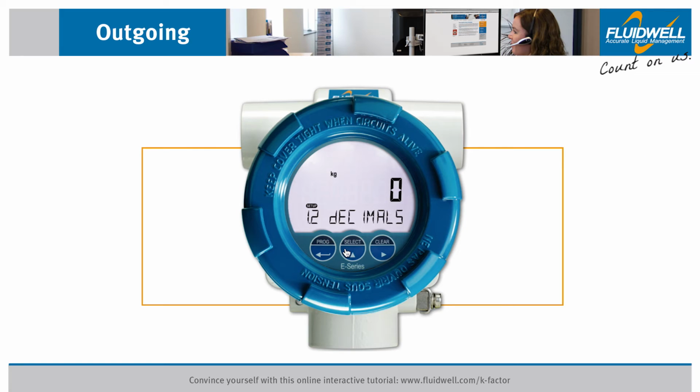Use Select to go to Menu 1.2 Decimals. You will see that the kilograms indication is shown. Press Prog to change this setting. We select the 0 value. Press Prog to store this setting. The decimals for the total are now set to 0 decimals.